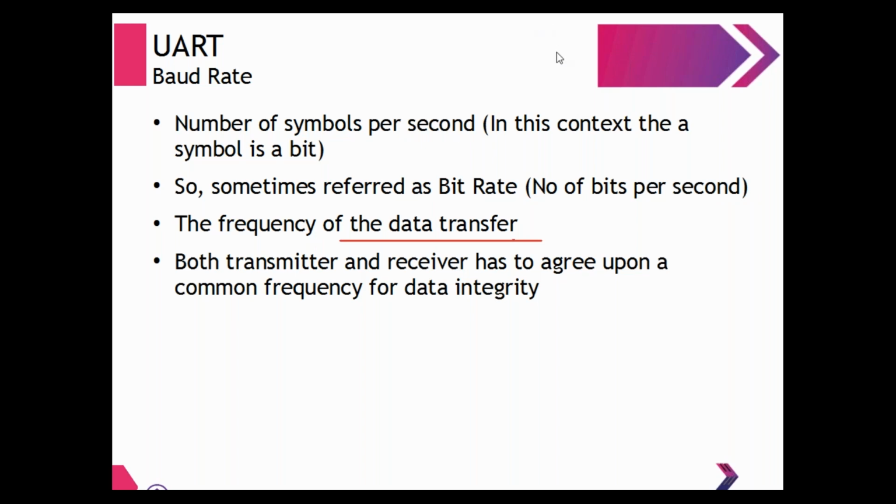And guys, last very important point: both transmitter and receiver have to agree upon a common frequency for data integrity. Both your transmitter and receiver must have the same baud rate, a common frequency. If not, then you will get corrupted data.